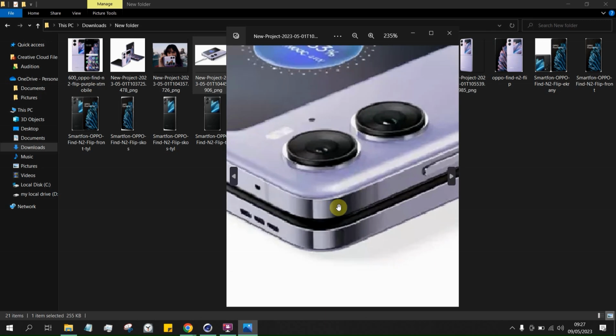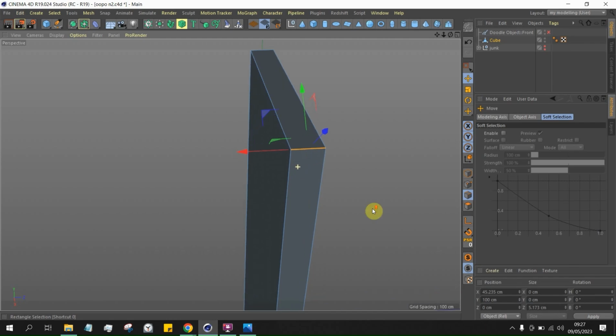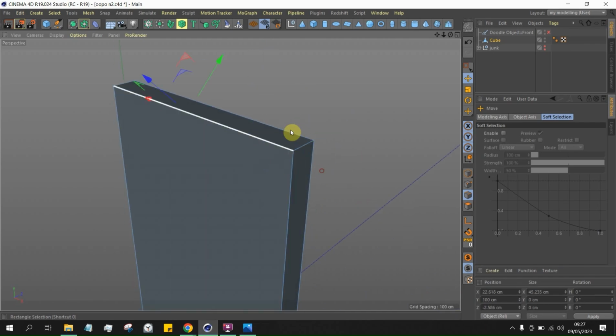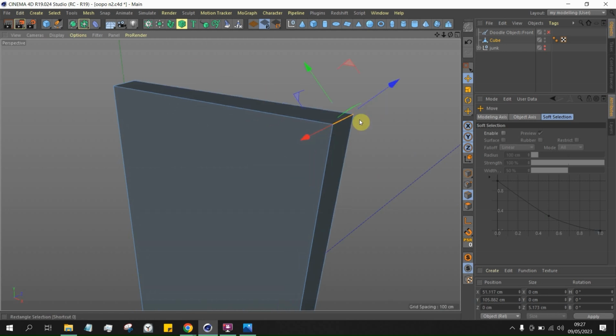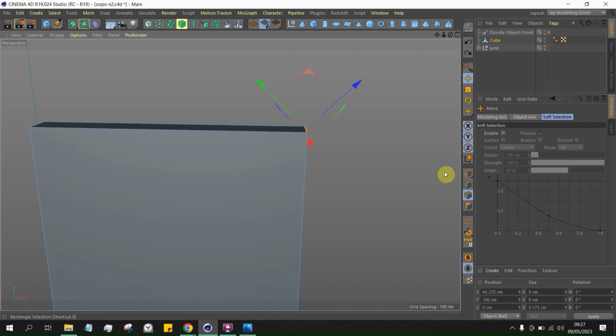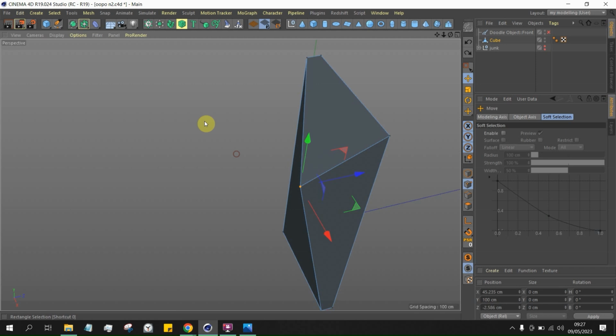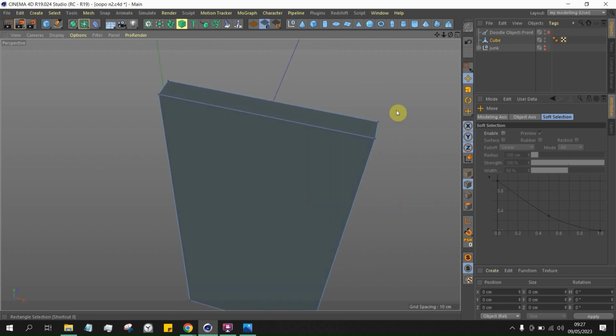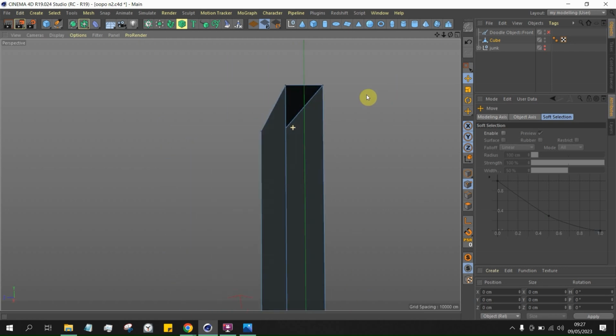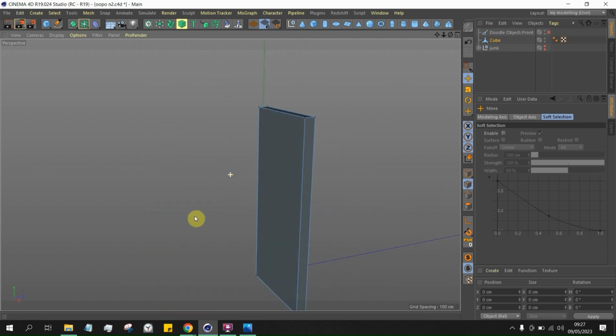All right, so this is a pretty simple shape. Normally with the iPhone you have to bevel every point, but this one we just have to bevel the side. But you have to check whether there are any openings. Okay, this looks perfect. If there are any openings, you can optimize the points by right clicking and going to optimize, or just press UO to optimize. So this is looking good. I like what I'm seeing now.